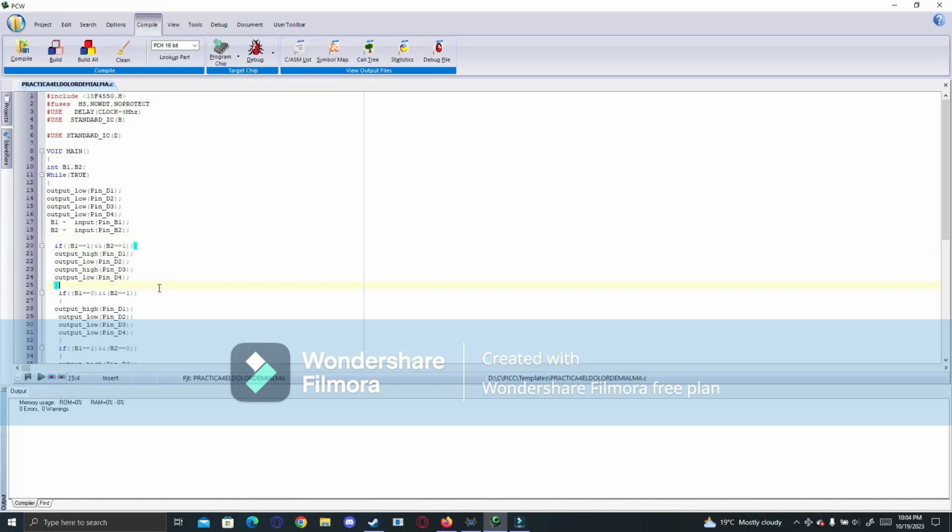We set up the condition that if the B1 is detecting a 0, meaning that there is a black tape blocking the light of the sensor, then it's going to turn off the 3 output, which is what makes the first motor go on, only keeping the motor 2 functional with the 1. As you can see with this pin, it's sending the signal as a high. So we're going to turn off P1 in this case. As you can see, this motor is motor number 1. It's the only one functioning, so it will make a turn using only this motor.